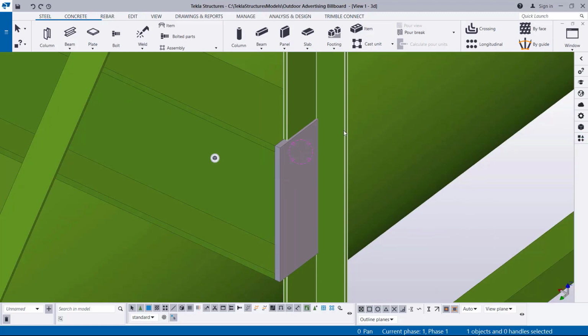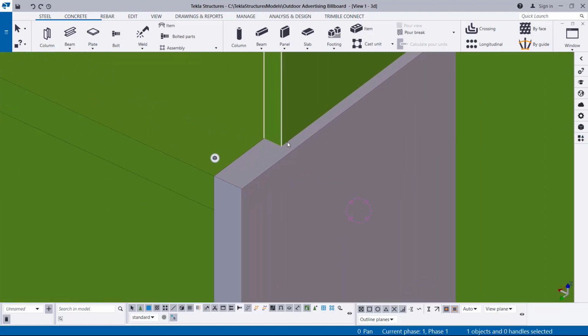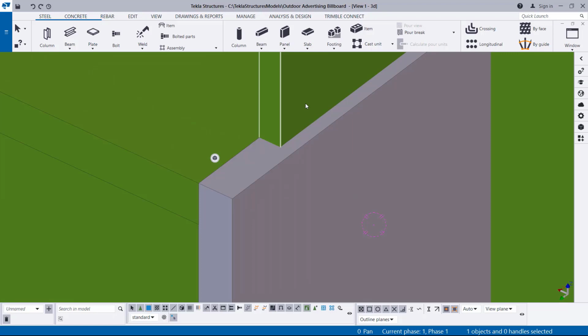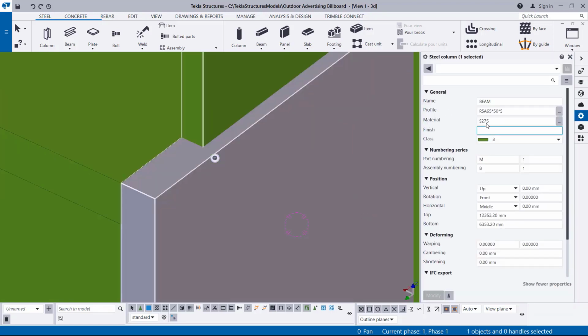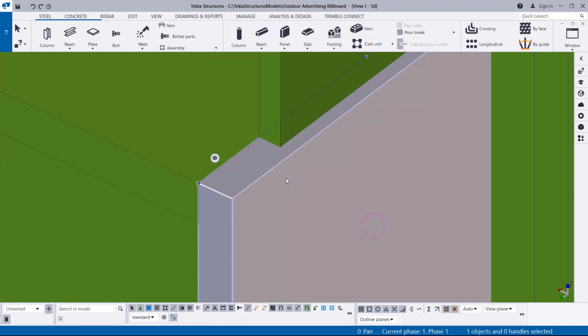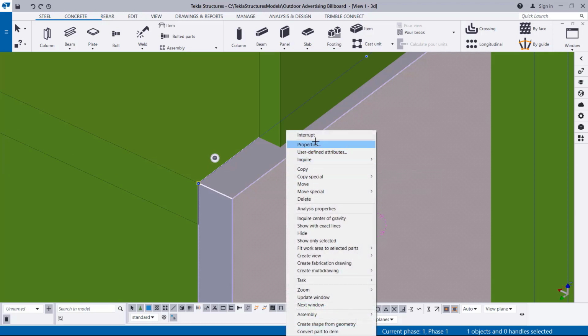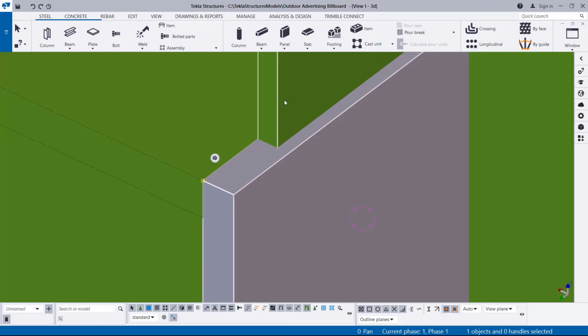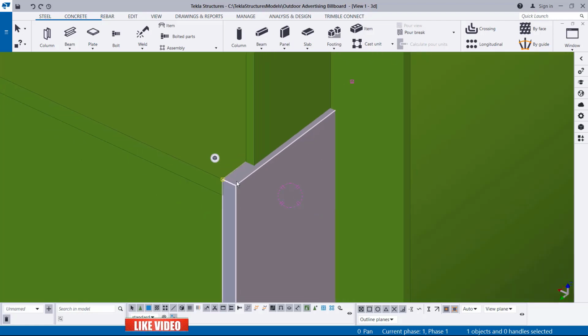So what do I do? I'm going to check the measurement here, or you don't even need to check the measurement. Just double click in here. You can see the thickness is 5 millimeter. The plate itself is 8 millimeters, so that is simple math. We have to offset this whole thing to be on the surface of this plate. We have to offset it by 12 millimeters.